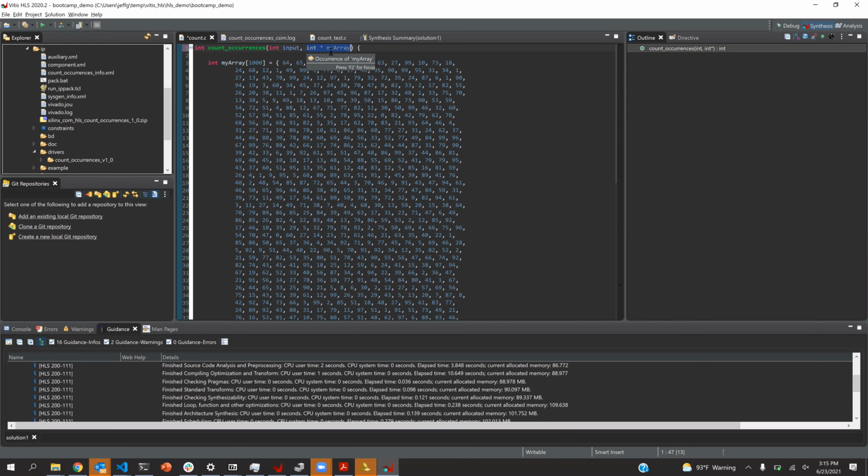So basically, I want to get data from any address. And to do that, we would insert a directive and say, we're going to make a master on the bus. Now we saw a bus connection where the CPU was controlling things, controlling our GPIO or our accelerator. Here we would make this be the boss, and it would essentially go into the processing system, and it would be allowed to initiate its own read and write operations to get data out.